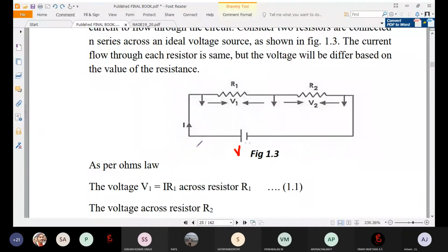Okay, so I told you, if you connect multiple resistors or multiple conductors together, the resistance will get added. Similarly here, if you want to calculate, you have to combine these resistors together. Otherwise, if I want to find the entire circuit resistance, I put it as R equivalent. So R equivalent represents the total resistance available in a circuit. Then I can simply apply I is equal to the total voltage, 5 volts, divided by the resistance. Likewise, I can easily calculate it.